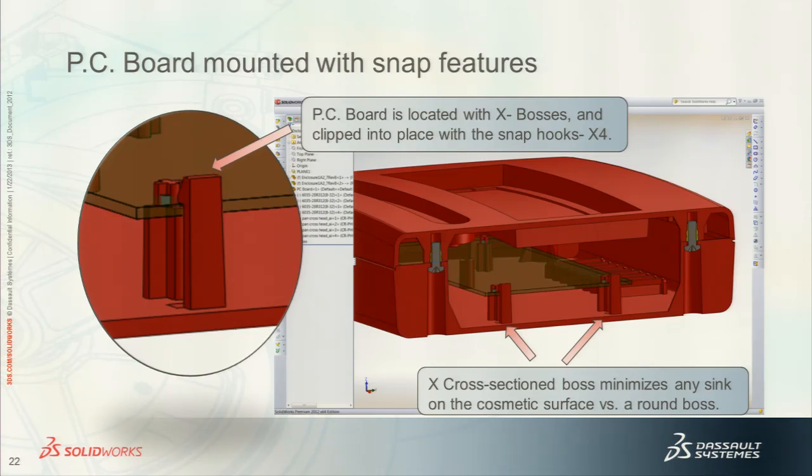Any questions on that? Yes? If you've got something that's subject to moisture, you use lifters to create snaps rather than that bypass. You didn't want the holes in the back. You can use lifters, but lifters are a more complex way of tooling something up where you do have undercuts. But that's another story. We can always talk about that more if you want to go into it further.